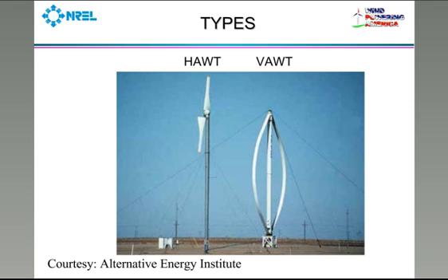The advantage of a vertical axis turbine is that all the heavy stuff, the gears, the generator, is on the ground. But that's also a disadvantage of a vertical axis wind turbine, in that it's closer to the ground, lower wind speeds, less energy output. The other piece is that they're limited a little bit on size, because you can see in this picture,